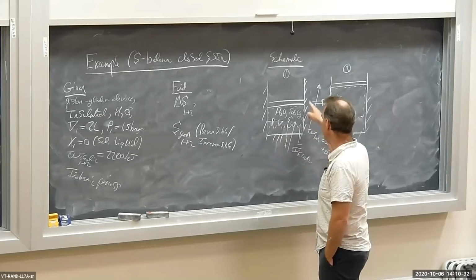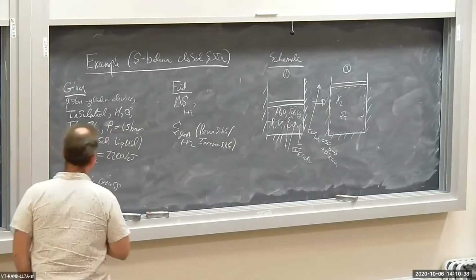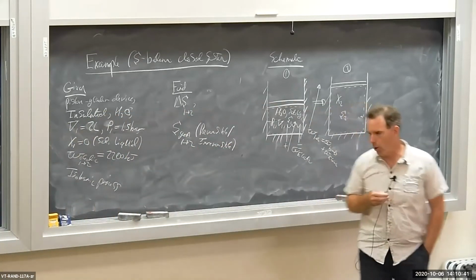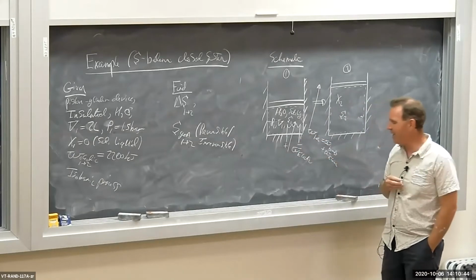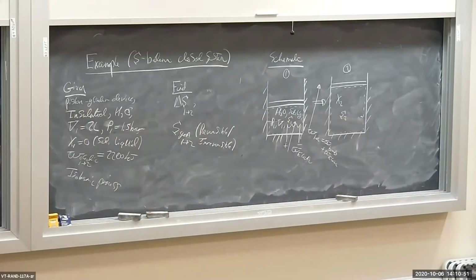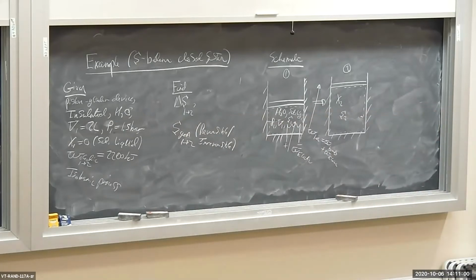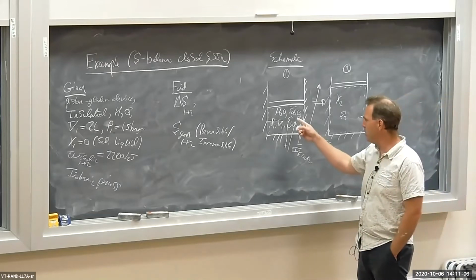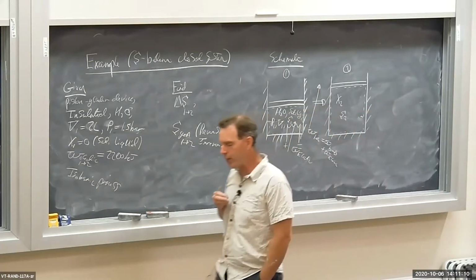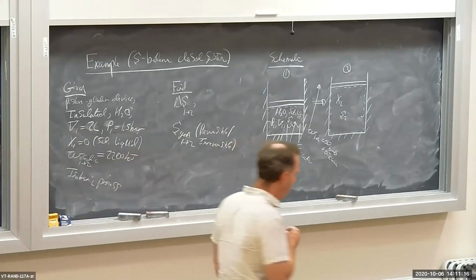Now, this piston cylinder device is insulated. So that's going to mean it's an adiabatic process. So if it's insulated, what are we doing with this H2O? Well, we have a little wire in here. So we're going to be doing electric work. How much electric work? 2,200 kilojoules of electric work from state 1 to state 2. So we're going to be heating up or boiling away some of the H2O saturated liquid. We're going to be boiling some of it away by heating it with a heating element. Also, the process is going to be an isobaric one. We're going to keep the pressure constant as we boil away the saturated liquid to presumably produce a saturated vapor.